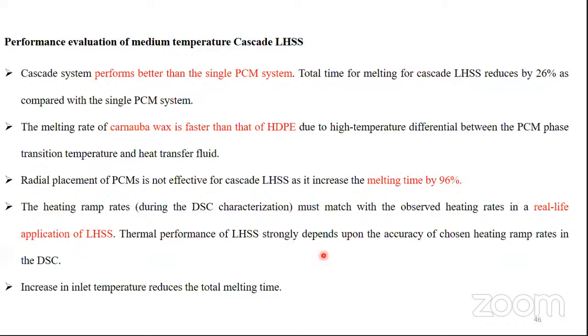Now the ramp rate is also quite important when we are doing the characterization of the phase change material, and it should be observed that the heating rate in a real life application of latent heat energy storage system should be compared with the heating ramp rate of that particular phase change material, so that we can properly judge the thermal performance of the latent heat storage system, which strongly depends upon the accuracy of choosing heating ramp rates in DSC. So increase in inlet temperature also reduces the total melting time.